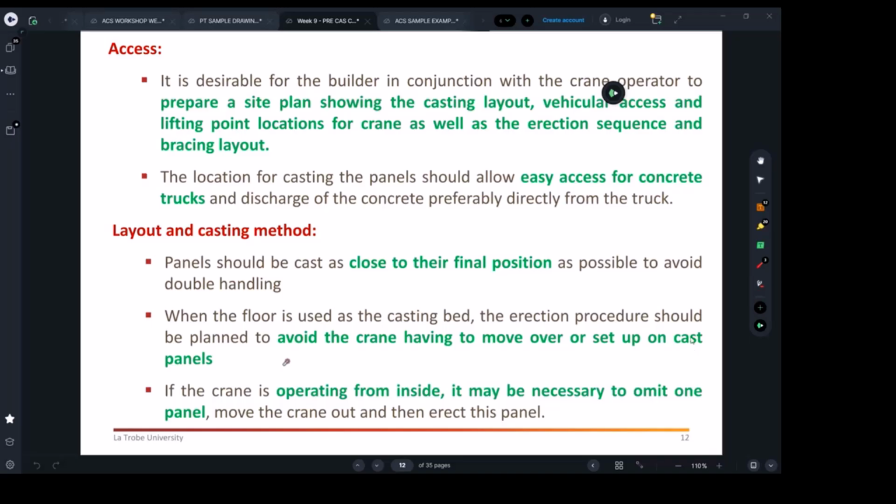We'll also need to consider the weather. If it's too windy, like what we had 2 days ago, it won't be a craning day for you. You should delay it, because there is a risk and safety issues there, as well as the positioning of the panels will be difficult to achieve with high winds.